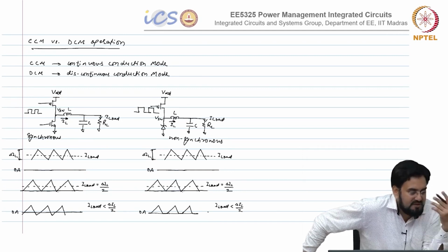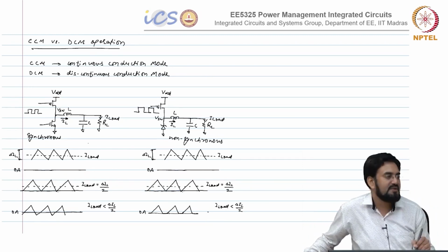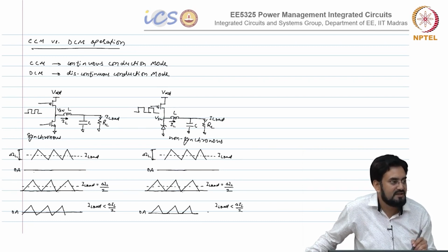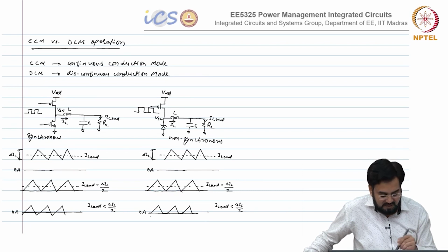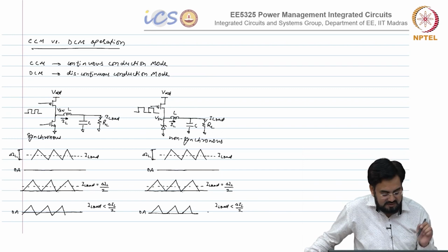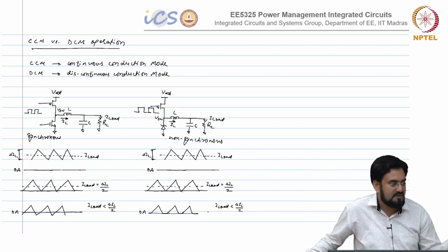So, you have a flexibility of reducing that voltage. So, the conduction losses can be reduced by choosing this, but since this is a synchronous behavior, you want a discontinuous behavior in order to reduce the losses. So, we try to force this NMOS to behave like a diode when the current goes below 0.